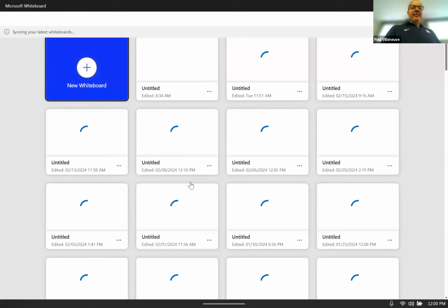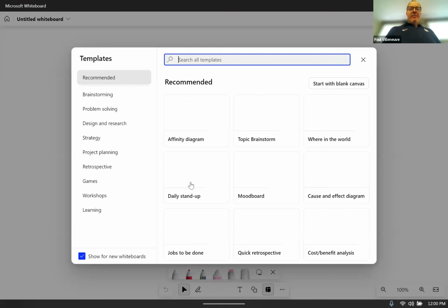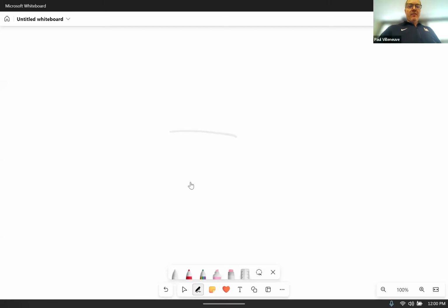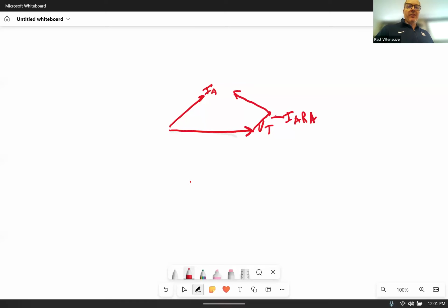So we just did a lagging. Let's do a leading. Help me out. My brain has turned to mush. All I know, here's what VT is. Can you help me draw a leading power factor? Like that? Yeah. Now, let's put I_A R_A like that, and let's just combine those two reactances. So this is my I_A R_A, and normally you can neglect it because this is usually much higher.